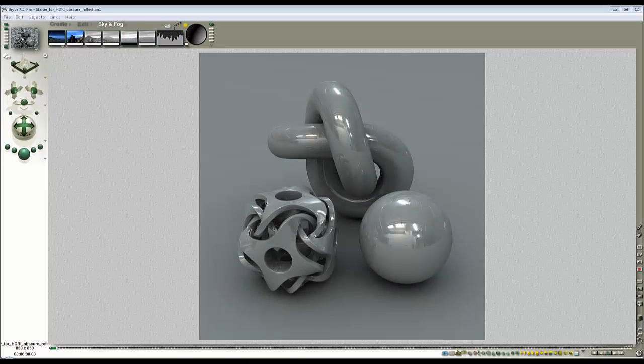Here then is the final rendered image and a little bit of a recap. So what we have here is obscure lighting driven by a specular convolved HDRI created by Horo, and the reflection being driven through extreme ambient material response on an exported version of that HDRI that wasn't specular convolved, a medium resolution one.